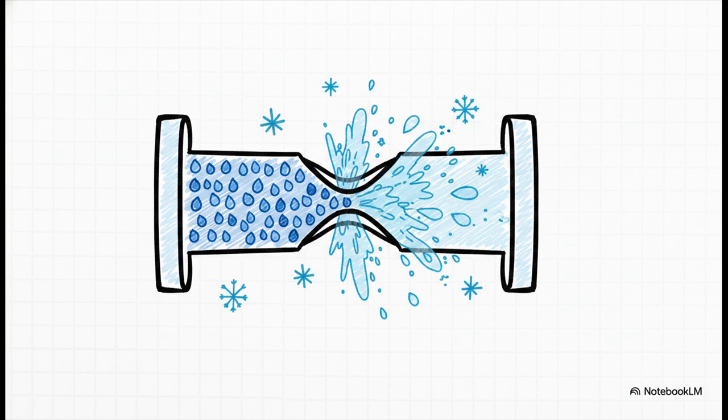This sudden drop causes what engineers call adiabatic flash evaporation. It instantly and drastically cools the liquid refrigerant down to a freezing temperature, perfectly prepping it to head right back into the evaporator coil to absorb more heat.